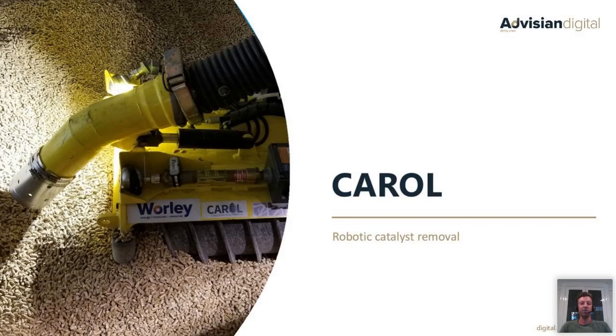For those who aren't familiar with catalyst changeouts and the like, pretty much every petrochemical plant, refinery, and LNG plant contains a number of these fixed bed catalyst vessels. Every couple of years, they open them up and send people in to vacuum up the granular material and replace it with fresh catalyst. During this process, people are sent down through manways that can be as narrow as 450 millimeters, or 18 inches, in diameter. They go down into these vessels wearing special breathing apparatus because the environment must stay inert, otherwise the catalyst will self-heat and ignite due to pyrophoric scale.